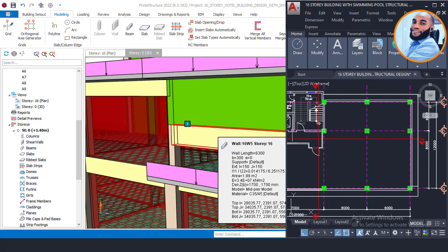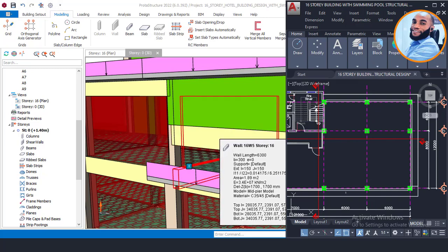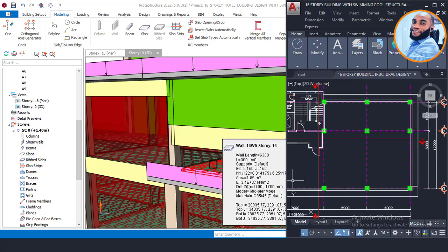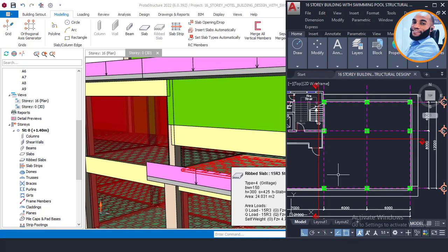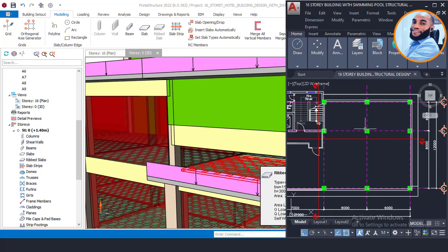So this drop down or this headroom has no issue because it is just a free walkway, and this headroom is around 1.9 meters or thereabouts. So I think someone can still enter there and come out without any form of obstruction. But since it's a free walkway, there is no bedroom here, no room, and no sitting room, nothing happening here, so it is okay. The person that drew the plan really did a good job.